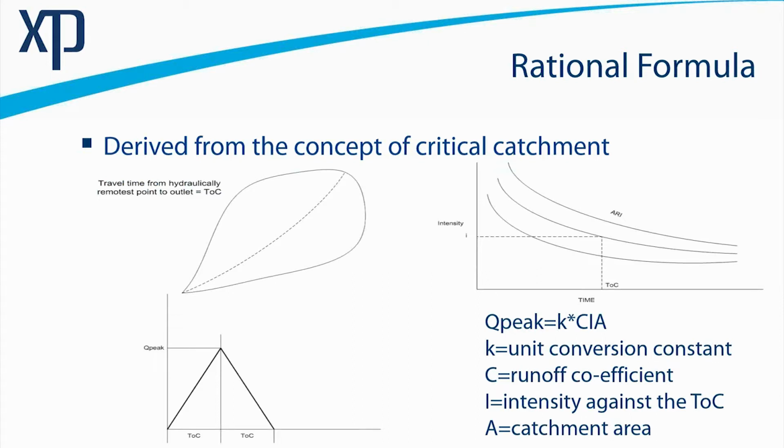I think it's a very good rule of thumb, but it is by no means the be-all and end-all of a hydrology calculation set. And by no means would I expect anyone to try and, unfortunately, use the word calibrate any other calculation back to the rational method. That would be an improper approach. The only thing that we can calibrate to is real-world data.